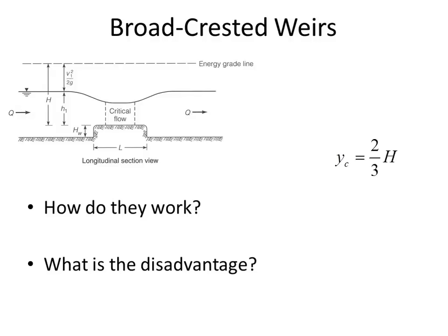I've been leading you astray by trivializing how easy it is to know the flow rate in the channel. I've been saying, let's say that it's 36 cubic meters per second. Well, that's usually a huge mystery. How much water is going through that channel is something that has stumped farmers and engineers alike for hundreds and thousands of years. Then they figured out that if you measure the depth of the critical flow, you don't have to measure the velocity.